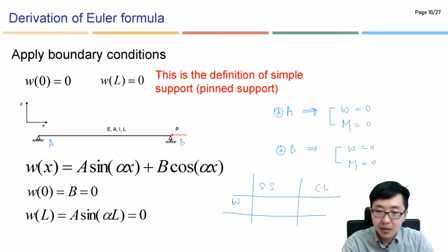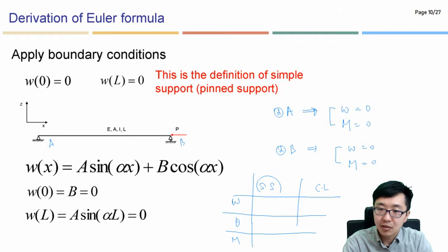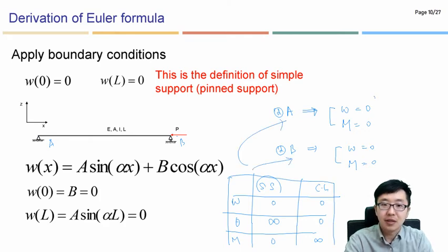Deflection, slope, and moment. In this case, the simply supported case, at both edges, that should be 0. Clamped condition: deflection 0, slope finite and 0. In the case of moment, 0. And yeah, this one I just brought here. Now you can understand what I'm talking about.